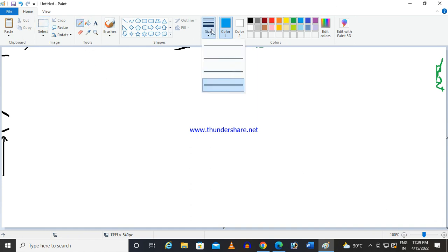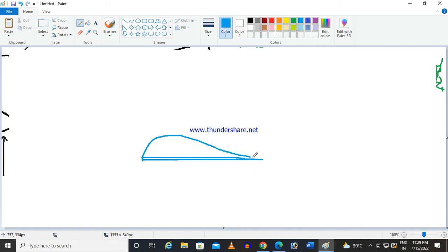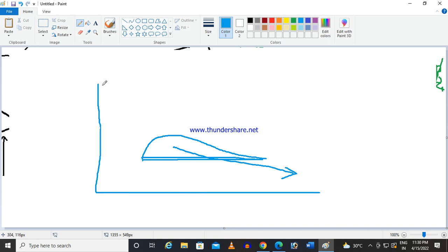In the next lecture, we are going to learn this problem through simulation. So what should be the steps? First, in a particular plane, we will create one drawing like this, then this part will be extruded to create the wing shape. Then we will go to the CFD module and define the computational domain.